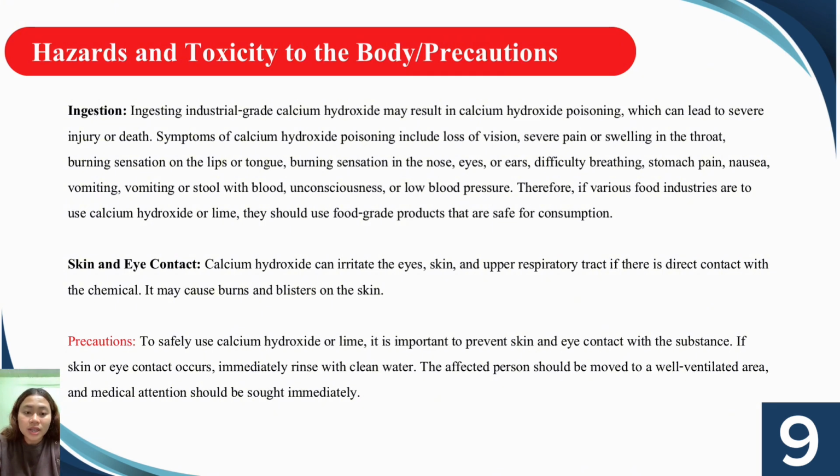Precaution. To safely use calcium hydroxide or lime, it is important to prevent skin and eye contact with the substance. If skin or eye contact occurs, immediately rinse with clean water. The affected person should be moved to a well-ventilated area, and medical attention should be sought immediately.